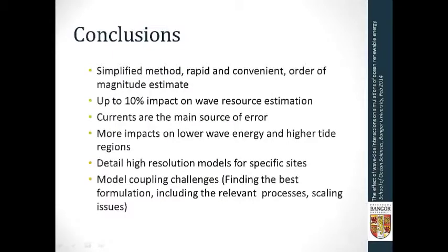That's a good question, because you can improve a model by calibrating it, or you can include more processes in it. There were two talks before this one about a high resolution wave model, and I'm wondering, instead of calibration, if somebody couples that wave model to a current model and gets a better answer, I think that model would be better than calibrating it, because if you're calibrating it, you might just change the physics, which wouldn't be right.